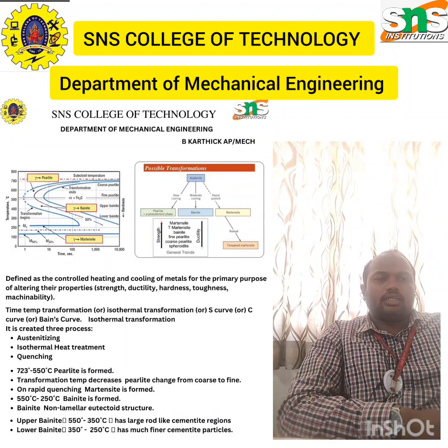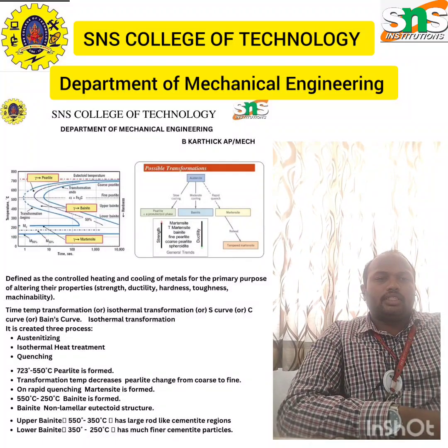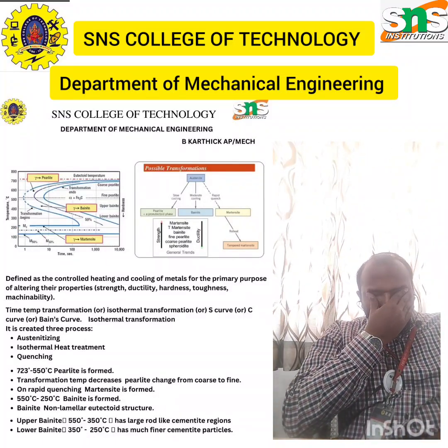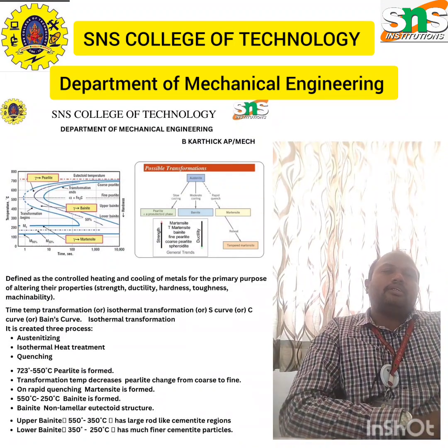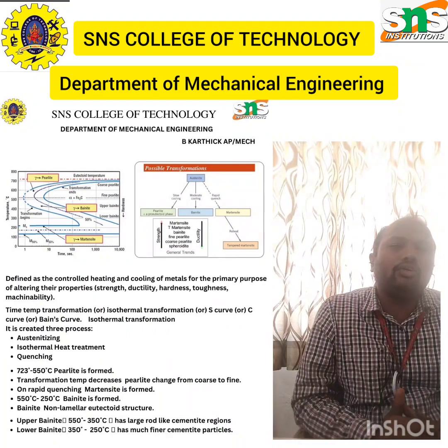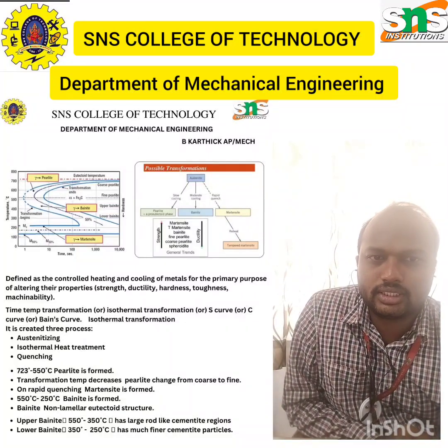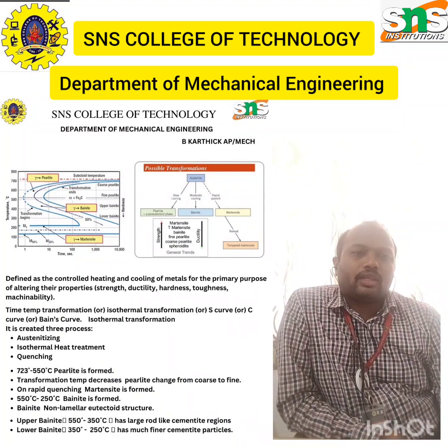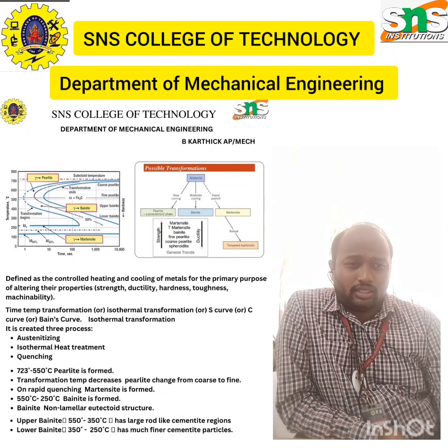The third one is the increase in specimen size. Once the specimen size is increased, a decrease in hardness will take place, because if the specimen size increases, there will not be homogeneous things happening, like heat distribution or load distribution. So upon specimen size increasing, there will be a decrease of hardness in certain spaces.